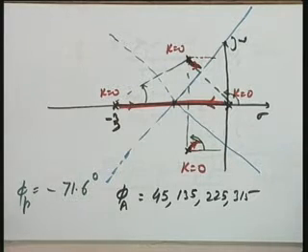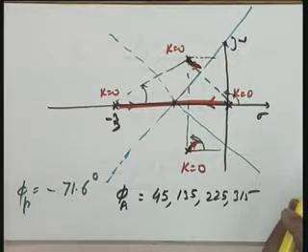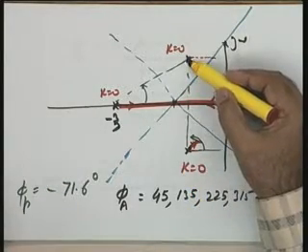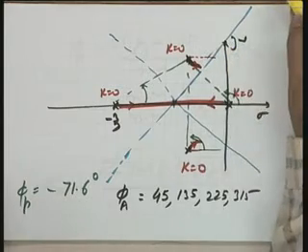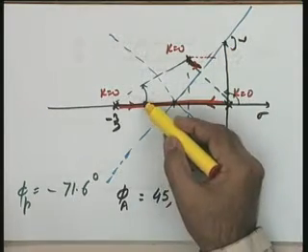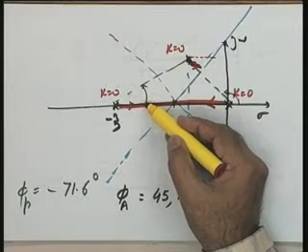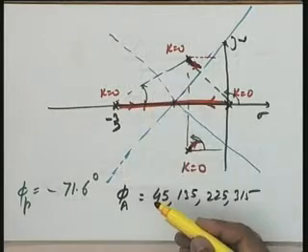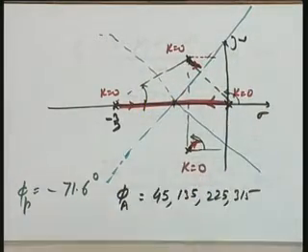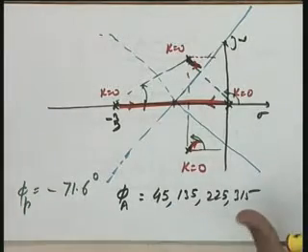So, the 4 root locus branches will terminate on these asymptotes only. Though it is to be proved, it appears that this root locus branch may go this way, this root locus branch this way to infinity, and there may be a breakaway point somewhere here, so that one root locus branch goes this way and the other goes this way, and the root locus plot is complete. This feeling comes intuitively from looking at this particular picture.